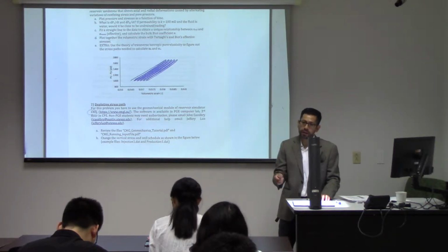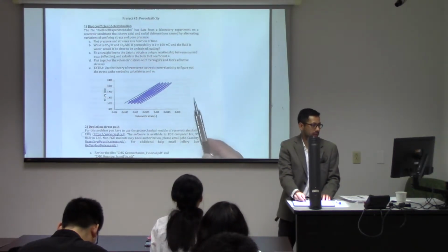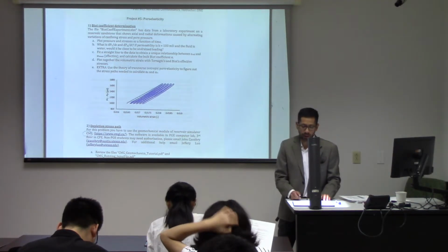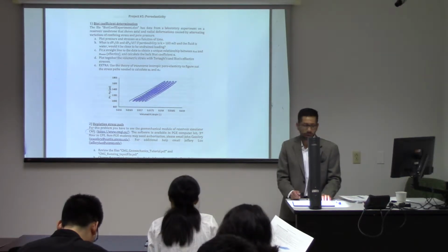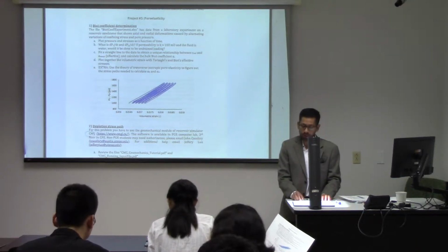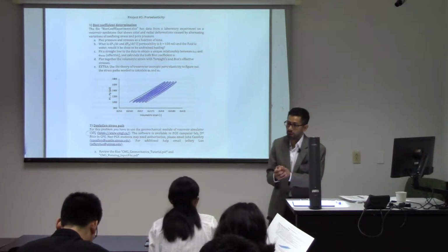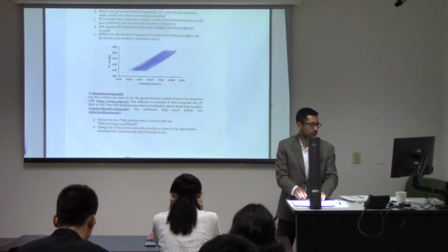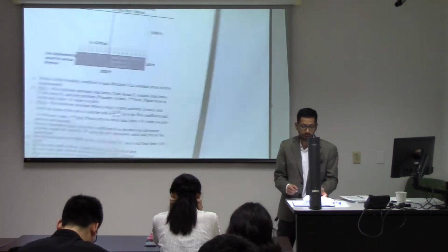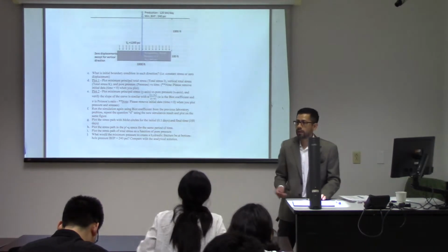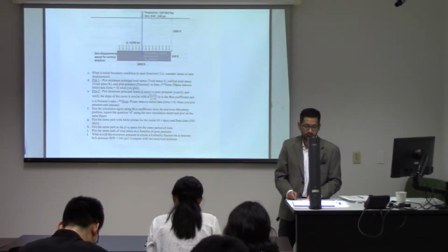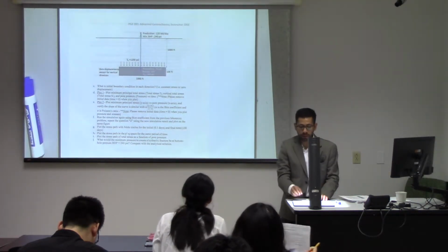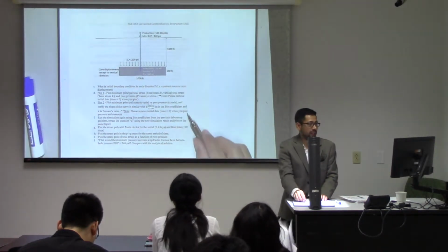But before you do that, you're going to have to calculate poroelastic constants out of a real experiment. I'm giving you the data here. So in order to solve this problem, we have to compute the poroelastic constants of the rock. And after we know the poroelastic constants of the rock, you're going to calculate the stress path with varying pore pressure.